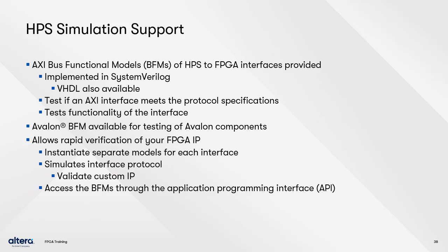AXI BFMs can also be used to simulate the HPS AXI bridges. Avalon BFMs are available from Altera to test Avalon component interfaces. With BFMs, you can rapidly verify your FPGA IP because it's quick to instantiate various BFMs for each interface and test them through the given API.